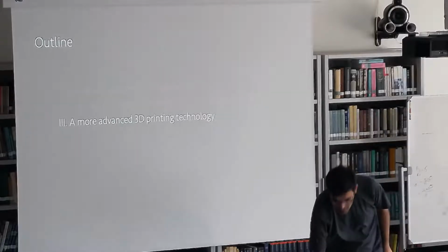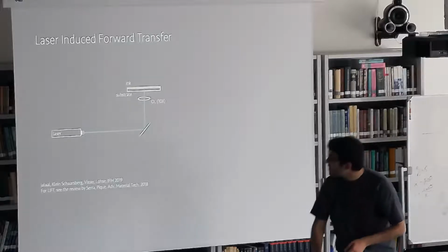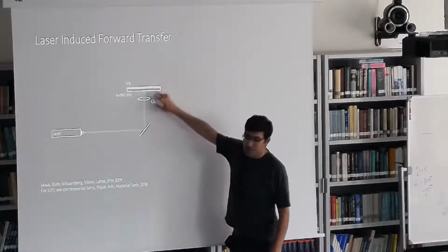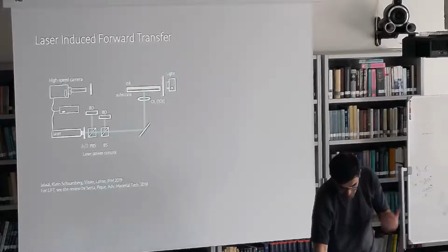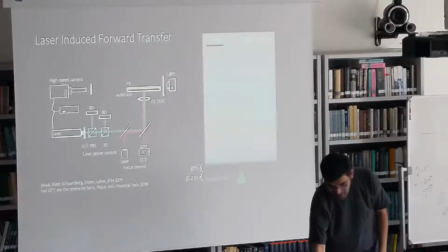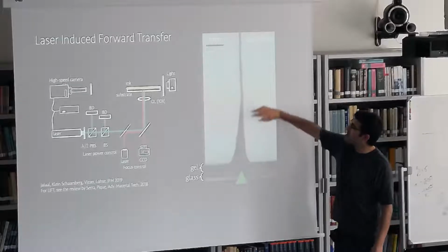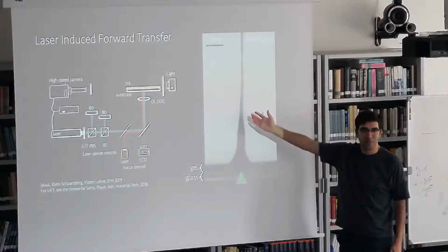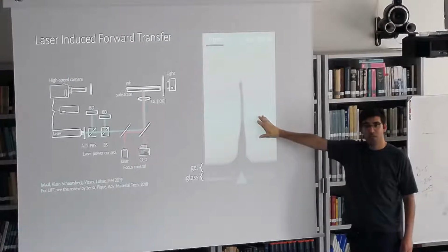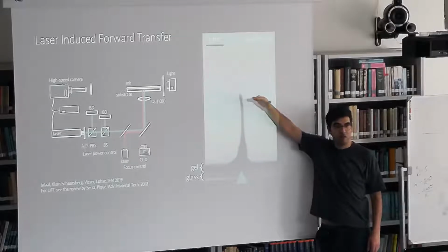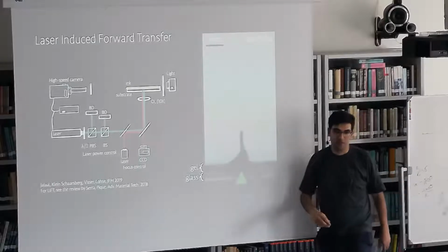And we basically started moving to systems that are laser based. So systems that look like this. We start shooting lasers at viscoplastic liquids. These are 5 nanosecond laser pulses, which we can control very, very accurately. And then, because of bubble cavitation, you start getting these jets that look like this. This is a very bad jet for 3D printing, but it's beautiful, so I'm going to show you. The idea is that if you control this jet, I can put a plate here, and I harvest the droplets out of this jet, and using that I can 3D print. And there's no nozzle, so life is much better.